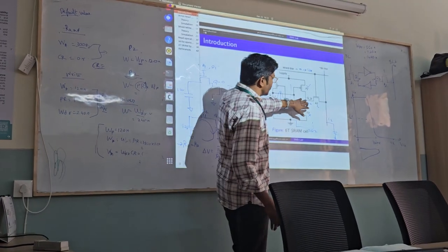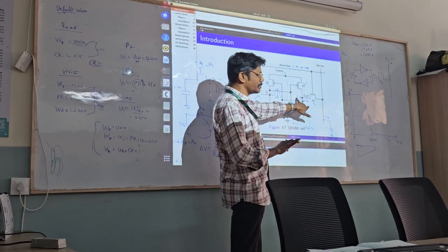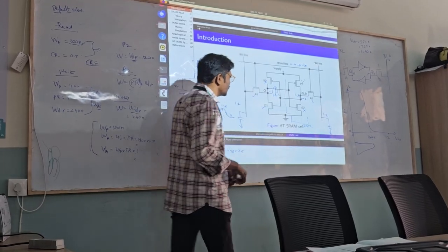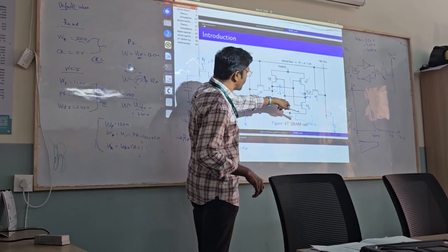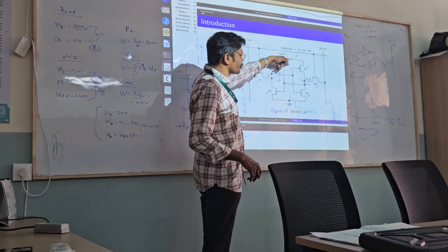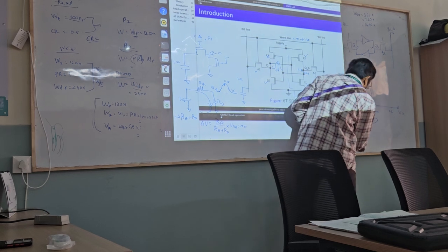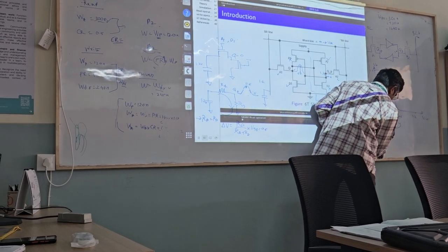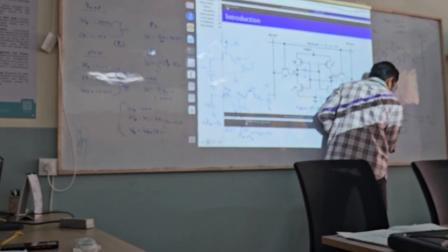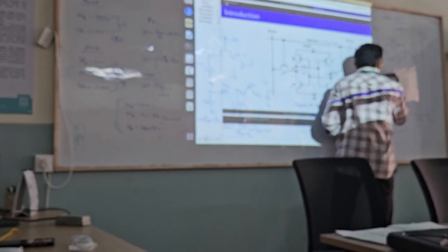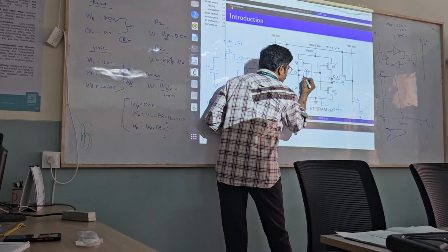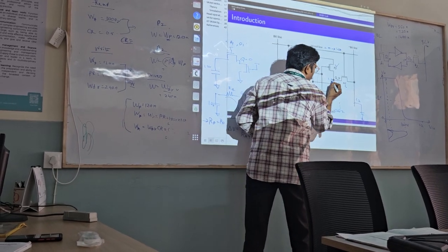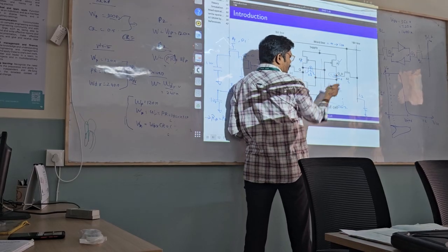So now this, I want to get rid of this. So what I can do is, instead of having this particular bump reaching all the way to 0.6, I will try to reduce the bump height by a certain amount. For this amount, I have to ensure that this small bump that I'm trying to create should not disturb the value across the output of the second inverter.